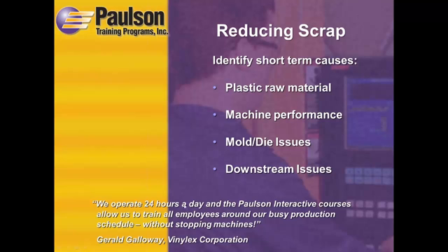And then there's downstream issues, obviously more relevant in extrusion, but what I'm really talking about here is even part handling, quality, inventory. Where do we put these things? Where do we put our parts? Are they cooled appropriately? You can warp a part by putting it on a table the wrong way. So all the parts need to be handled appropriately, depending on their process.